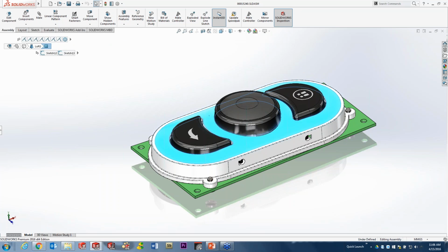Now, as I select this, what we're getting here is a hierarchy. So what we see here are faces, features. The features have their sketches buried beneath those. And then the body, the part that's part of that face. And then the assembly and potentially a higher structure here of subassembly structures. Now each of these icons will give you the toolbars or the buttons that you would see by selecting these features in the graphics area.